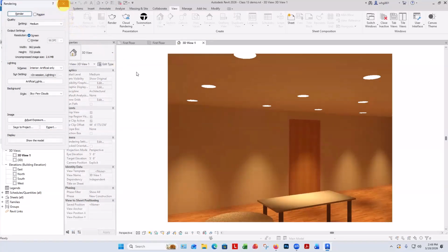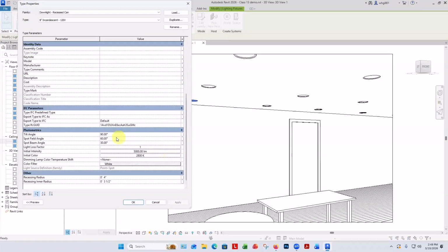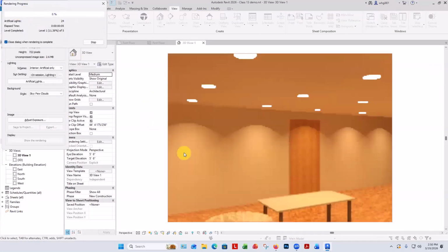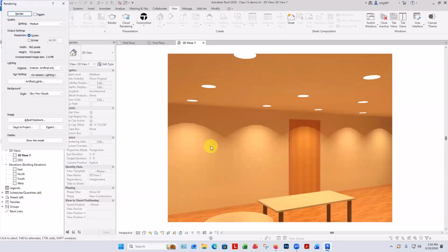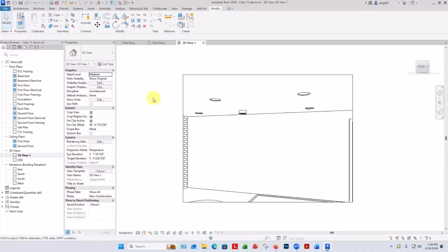And if I make them the same, the full brightness will come right out to the edge, edit type. If we make these 2 angles the same, I'll make them 60 and 60, so it stays up there on the wall. Render again. We should be getting a very hard, okay, so it's moved up, and we're getting a very hard edge right there. So as you play with those, experiment, let's say, do your research to see what you want and how you want those to work. I've cut out a couple of minutes where I couldn't get a wall washer to behave. You'll see it popping up shortly.